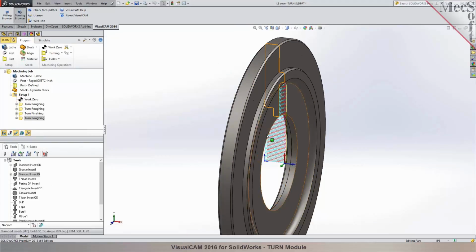Now if you already had a pre-drilled hole in here, so this particular blank that you're going to be starting with is 4 1/4 inch, does it have a pre-bore on it typically? No, it's going to be plain. Okay, so are you going to be boring this in a turning operation, or would you want to use a milling operation to bore the hole? No, we're going to bore it in the lathe, right?